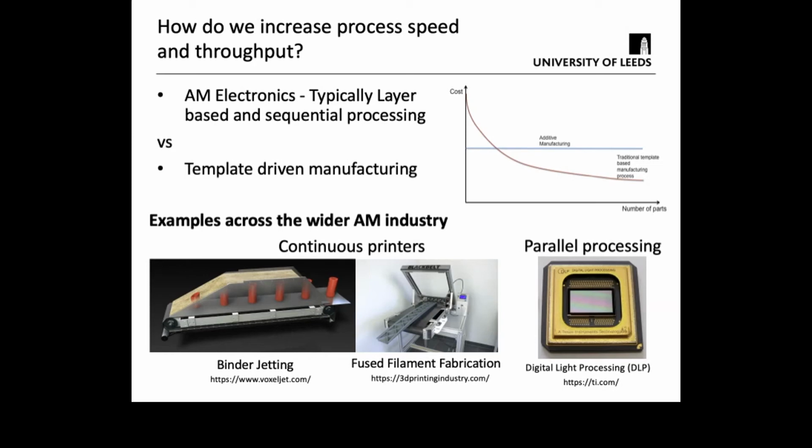I don't know the answer to this, but if we look at some of the aspects in the wider additive manufacturing industry, maybe we can start to take inspiration. In recent years, you've seen some nice examples of moving from a fixed platform where after every print you would take the part out to continuous printers, using things like conveyor belts. You've seen it in binder jetting, and there's been a recent flurry of activity in the fused filament fabrication market. So are things like this, where you can just run the printer 24/7, will that help?